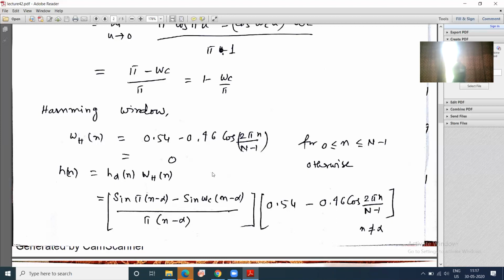If I look at the Blackman window or other windows, they have even more complex expressions. But essentially, it requires more hardware. And why is it used? Because in some applications it is desired that the passband to stop band transition has to be very fast. Even if it is not possible to reach the ideal, we can reach better and better in different kinds of windows.